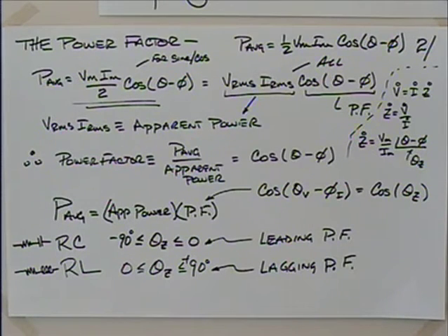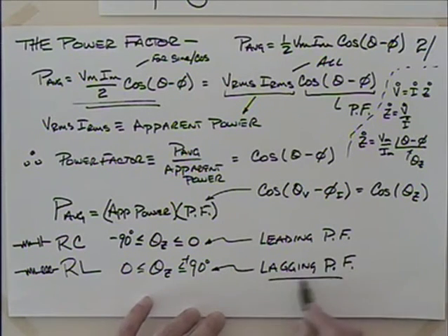Predominantly inductive, right? Where's a big source of inductors? Windings, motors. You ever hear about people that rewind motors, put the windings back in motors when they burn out and things like that? Yeah, motors have a tremendous amount of inductance. So a lot of industries use a lot of motors, so it's probably more common to have a lagging power factor.